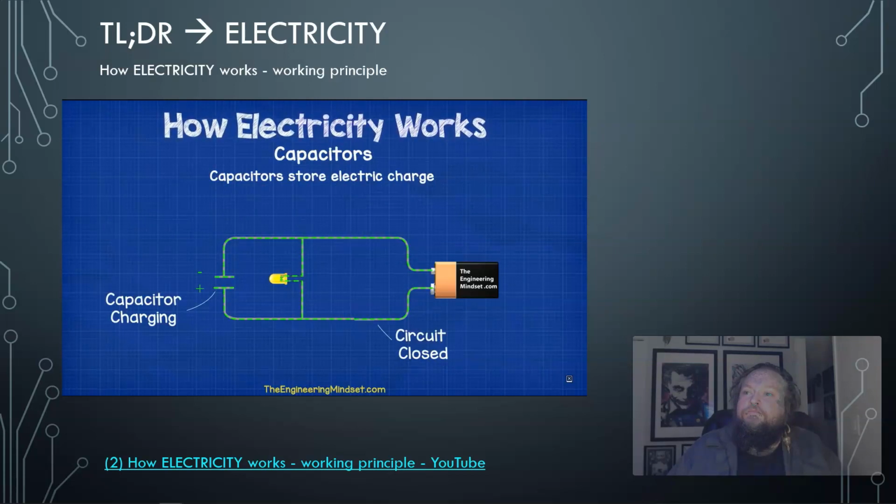Now something else which I just want to briefly mention is the capacitor. A capacitor forces positive and negative charges to separate across two plates when it is connected to a power supply. This causes a build-up or store of electrons within an electric field. When the power supply is cut or interrupted, these charges will then be released, flow up and meet again. This provides a power source but only for a few seconds until the charges have paired back up again. It's slightly similar to a battery, but capacitors are very common and they're in almost every single circuit board. We'll cover this in more detail in a future video, just be aware of these.